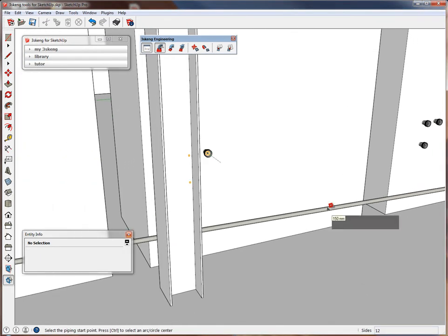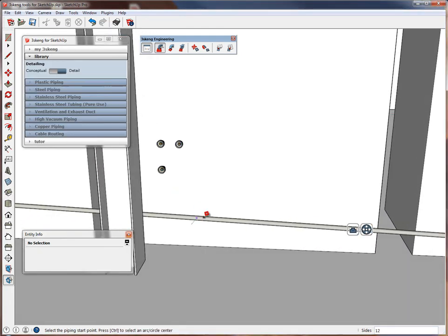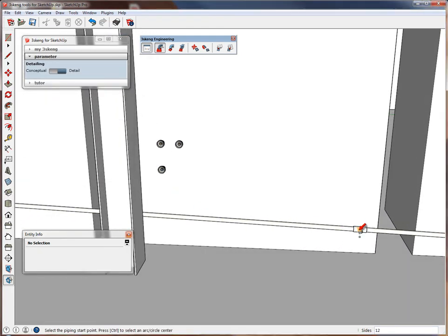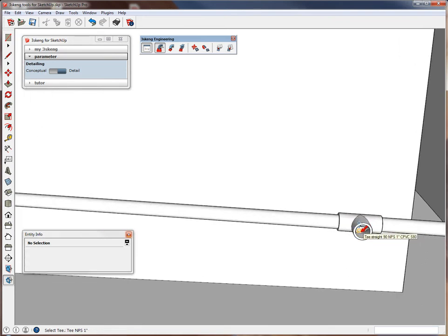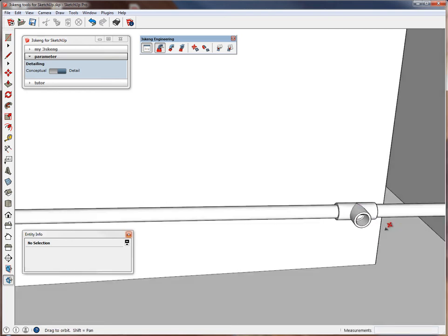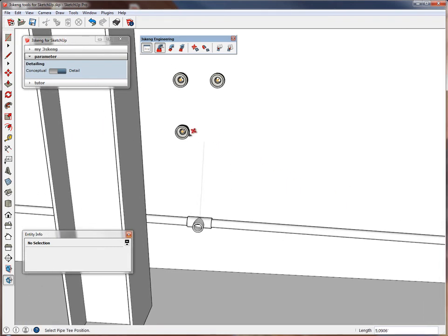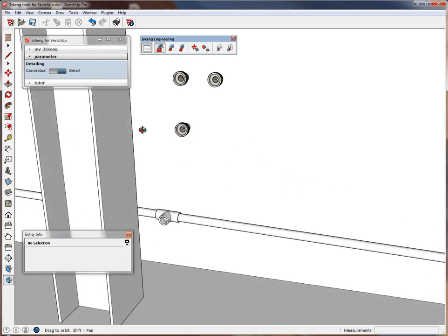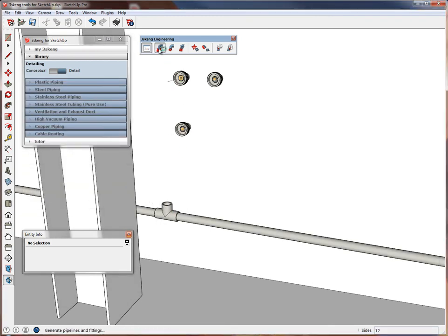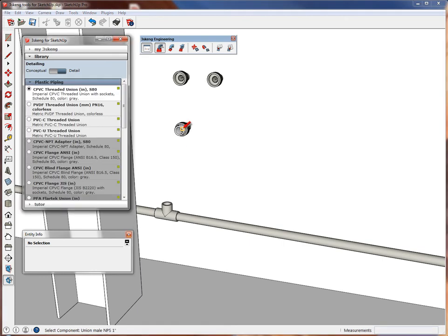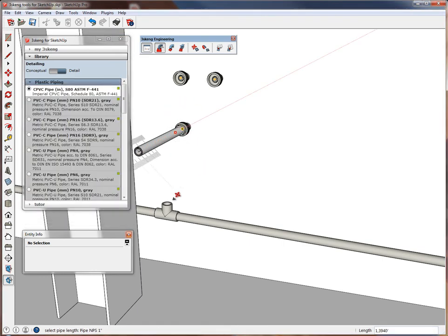To make the connection between pipe and our drain, we click the T button on the pipeline. We are shown the available T's for that size. It's a reduced T, 1 to ½ inch, 1 to 3/4 inch, and 1 to inch as a straight T. When we pick it, we are asked for the final connection, and we will pick the reference to the female union. Have it face upwards. Now we have to apply the counter union and can use the auto pipe function of the detail to get the available connections with 45s and 90.